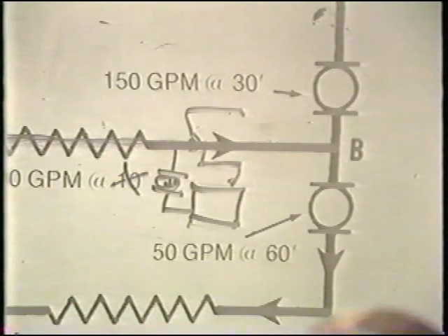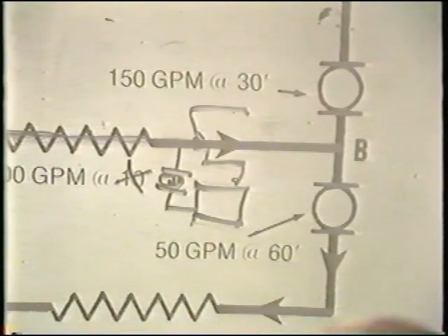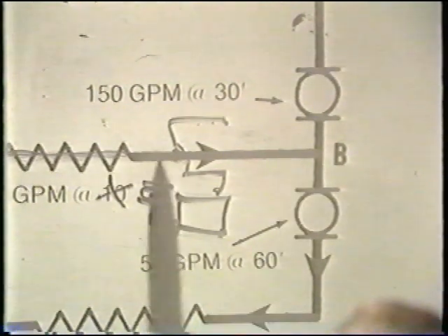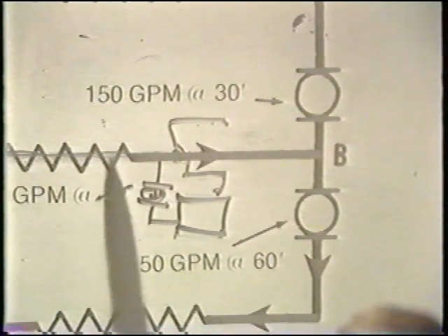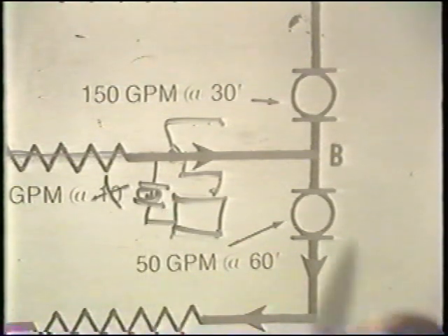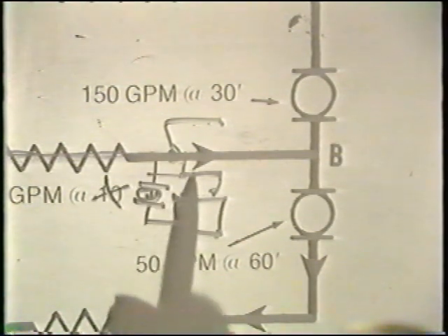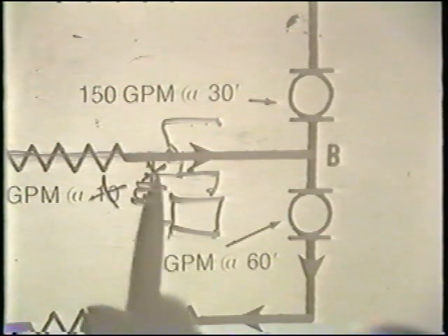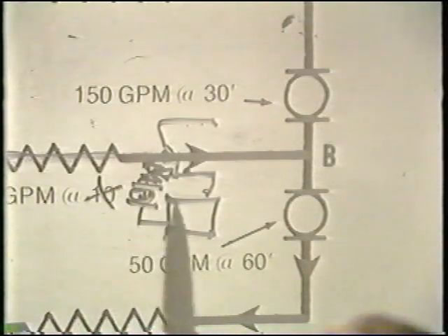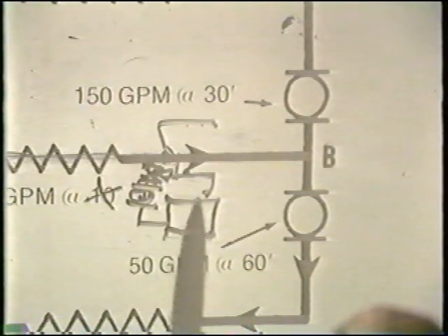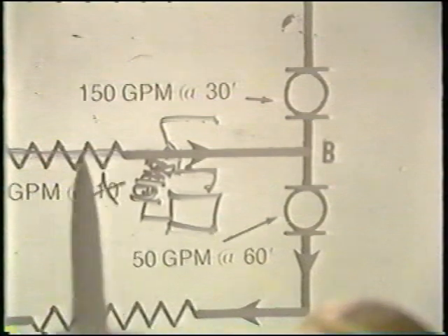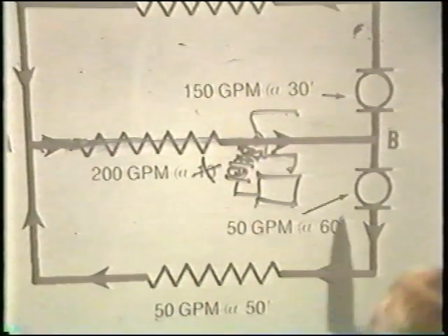We can then provide a separate pump, but establish at all times that the pressure drop from A to B will be consistent and will not change despite changes in the reset scheduling, for example, of a boiler, in which the reset valve is placed in this circumstance in the secondary circuit, so that we then have that single consistent head loss from A to B.